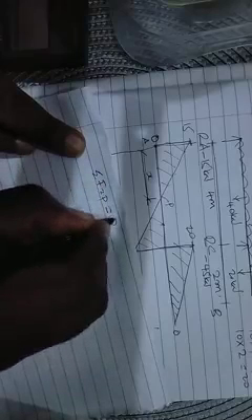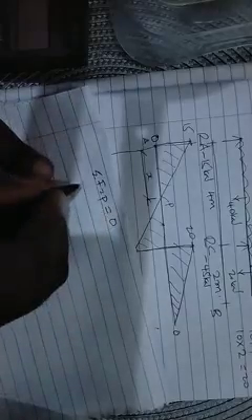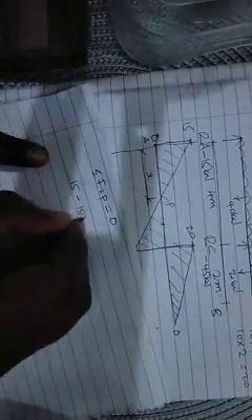We have the summation of forces at point P equal to 0. So 15 minus, over distance x we have 10 kilonewtons per meter run, so it will be 10 times x, acting at the center of this distance, is equal to 0.